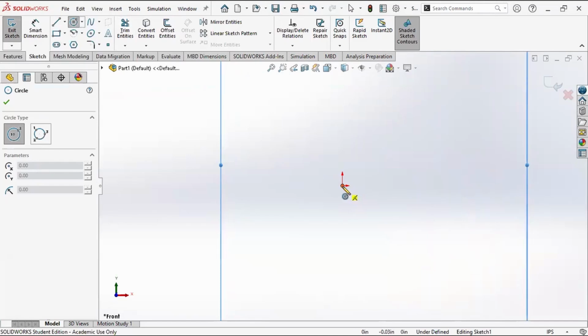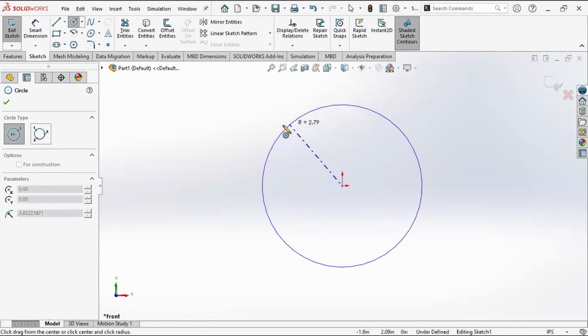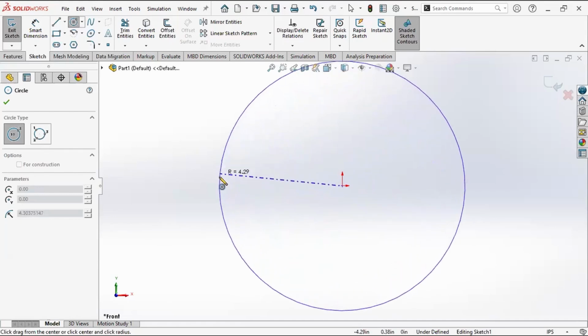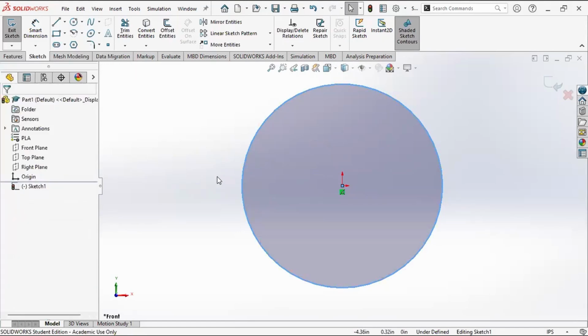And if I highlight, I can see an orange dot here at the origin. That means that if I drop the point there, you can see next to my cursor the little yellow coincident constraint marker. I can click and it will automatically add a coincident constraint for the center of that circle. And if I just move my mouse, I'm not holding down the left mouse button. I just click the once to get my point. And if I drag it out, I can create my circle.